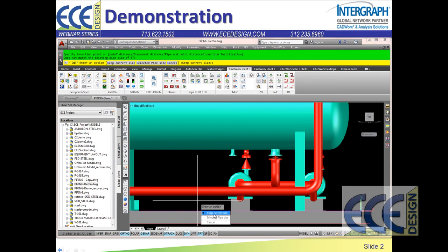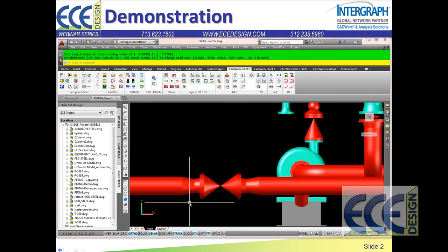And you'll note that the system says, hey, wait a minute, you're set to 6, it's 8-inch. Did you really want an 8-inch valve? No, I want a 6-inch valve, so I'm going to keep my current size. And this says, okay, well, if you're going to do that, you need a reducer on this end, which one you want to use. And you will also need a reducer on this end. So I select my reducers. Now I've got my 6-inch control valve in my 8-inch line.